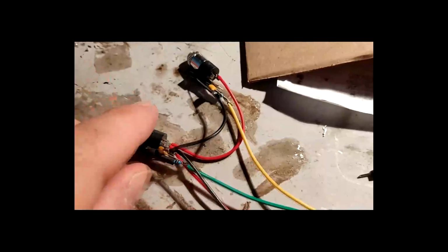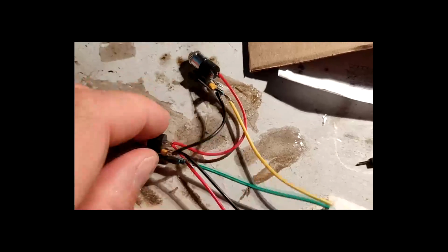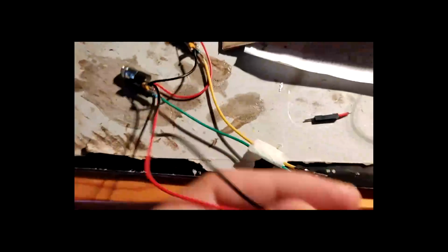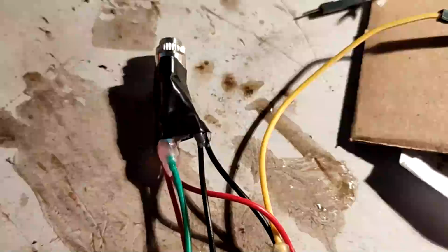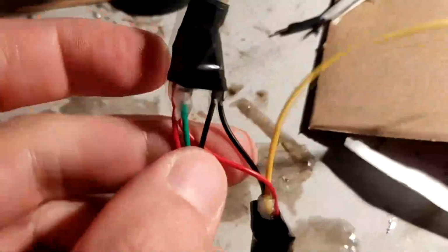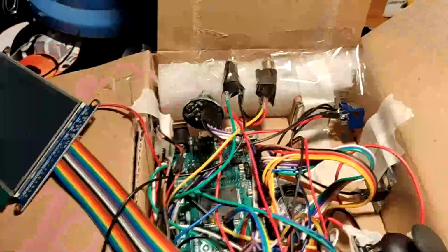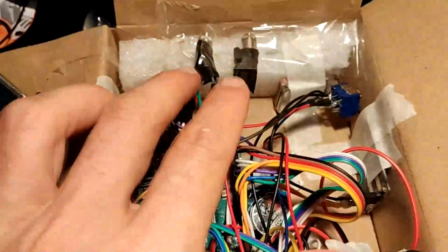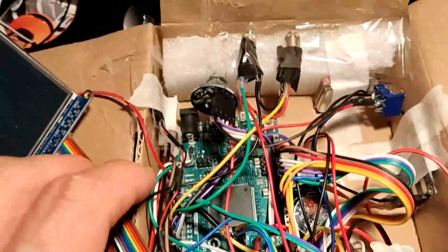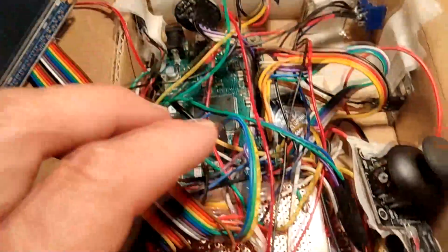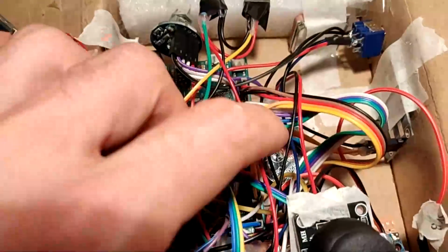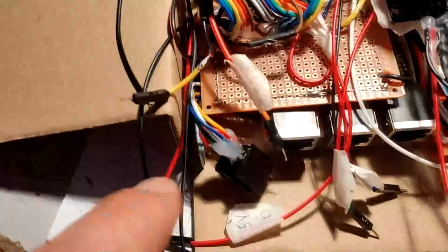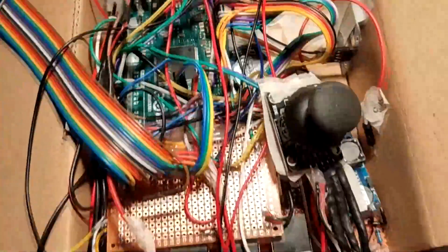To save some space, I've connected the two black and red wires of these jack connectors so there are only two wires for the power supply and two wires for the Arduino board. I've put some hot glue and tape to isolate the two jack connectors. I put the two jack connectors on the top; maybe in the final version they will be on the side. They're going to be supplied with the 5 volts buck. As for the speaker, the joystick is on 5 volts Arduino, the RTC module is on 5 volts buck, the Bluetooth module on 5 volts buck, and the GPS module on 5 volts Arduino.